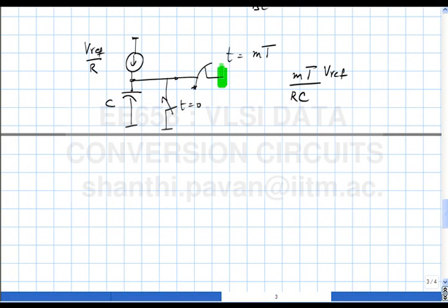That is a measurement of the RC time constant. You can use that measurement to figure out what to do with the programming bits of the digitally programmable resistors and capacitors. Is that clear? There are a bazillion ways of finding what RC is. All of them will have to involve some kind of dynamic measurement, because you are interested in measuring the time constant of the RC network.